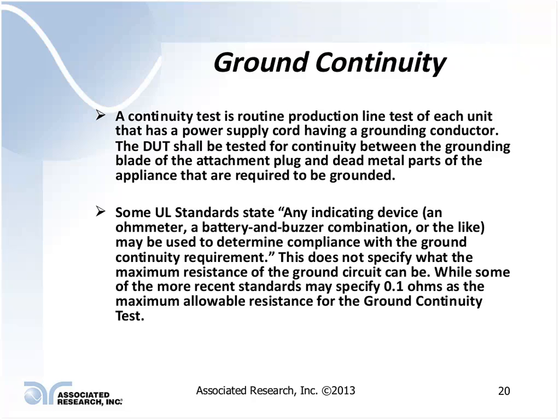If you take a 120 volt circuit, and let's say it has a 15 amp fuse, that fuse can carry 30 amps of current for 2 minutes without blowing. So if I take 30 divided into 120, that comes out to 4. If the resistance of my ground circuit is higher than 4 ohms, it will never allow enough current to flow in the circuit to allow my fuse or circuit breaker to pop.